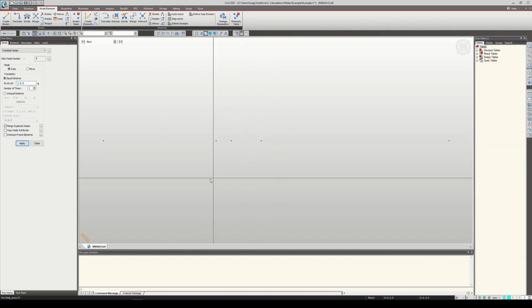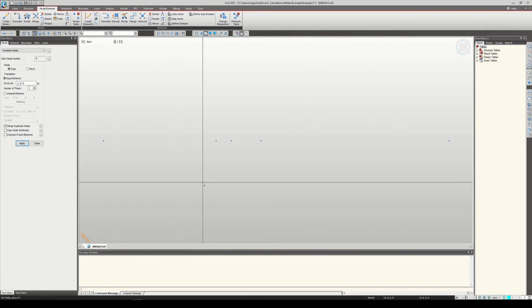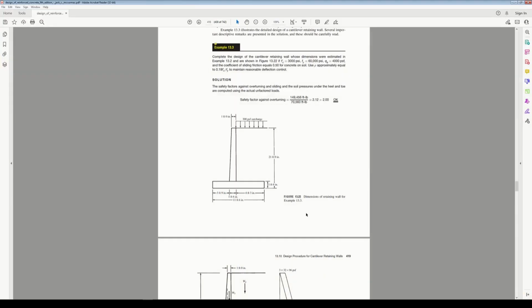There we go. So now, if you want to measure the distance, if maybe you made a mistake, you can do that by clicking F4. Just close this. F4. This will pop up, and you can click your first node, your second node, and it'll tell you here, 3.75 feet distance from node 1. You can go from here to here to double check, 0.5, here to here, 1 foot, from here to here, 6.25. And does that match?